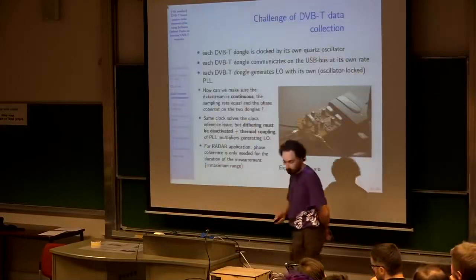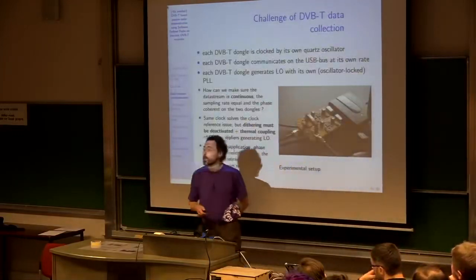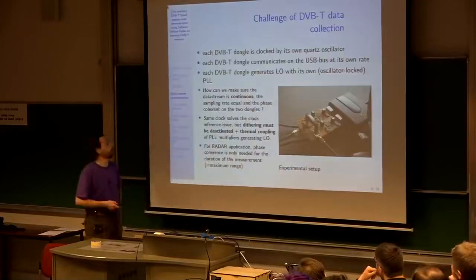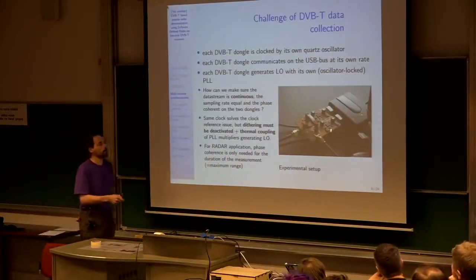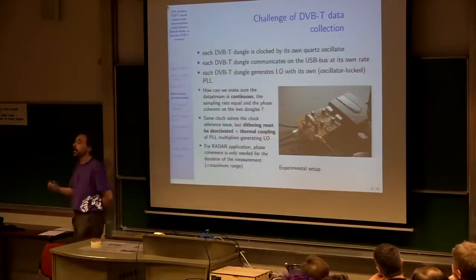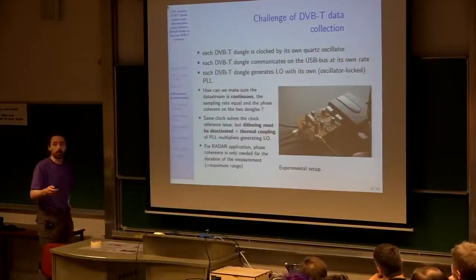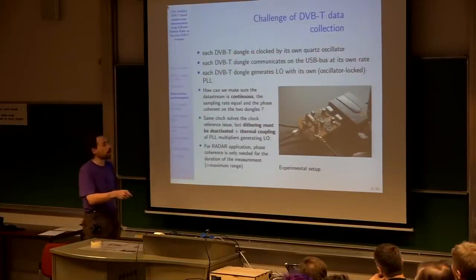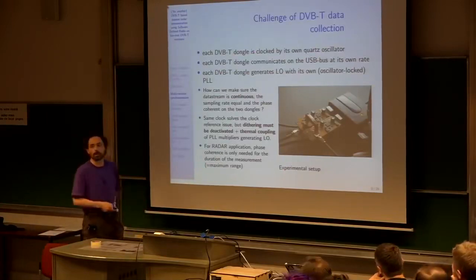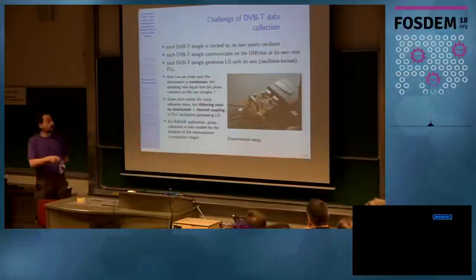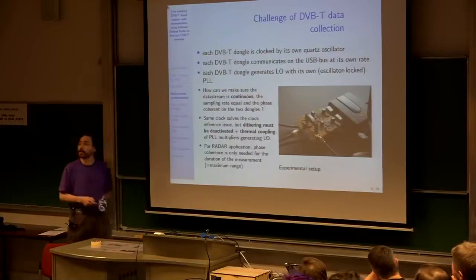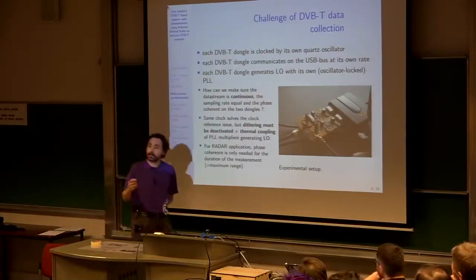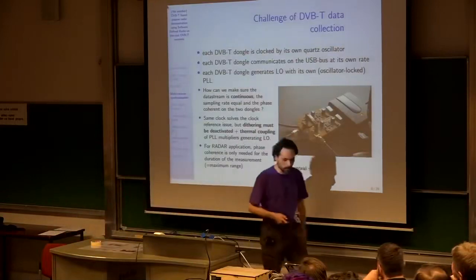Okay. So we know we can compute the cross correlation in GNU Radio. That's easy enough. Now, how can we actually measure data and not use simulated data? The challenge is, of course, you put two DVB-T dongles, one connected to the reference antenna, one connected to a measurement antenna. And the question is, are they synchronous? Are they locked in frequency? Well, frequency locking is just a matter of unsoldering one of the clocks and connecting the frequency source of one DVB-T to the other one. That's easy enough. However, the carrier frequency, the local oscillator, is generated by using a PLL, and you don't know how this PLL is implemented. The second question is whether the data stream is time synchronous. That's the second story. And the last issue is phase synchronism, which will be tackled in the conclusion.